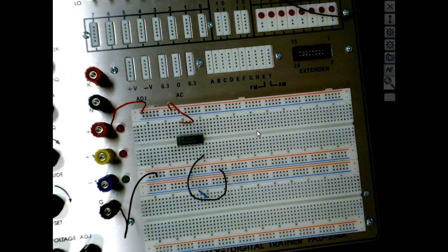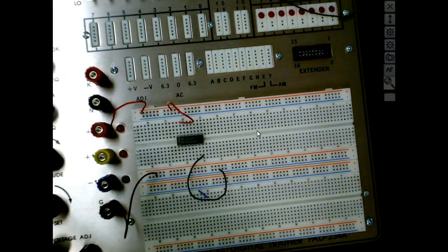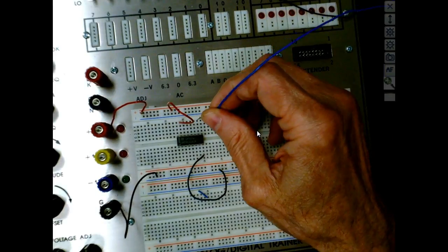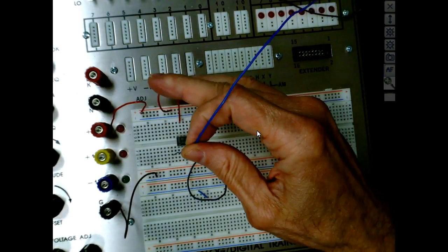So what does it say we need to do? For all the circuits, use the trainer switches. Okay, so we're going to use the trainer switches, and we're going to use the LEDs for the output, right? Open some of the data switches. So we're going to use the select. So I need selects, right? So what do we use? We'll just use 0, 1, and 2. So what's the select pins? Yeah, for the 74151.